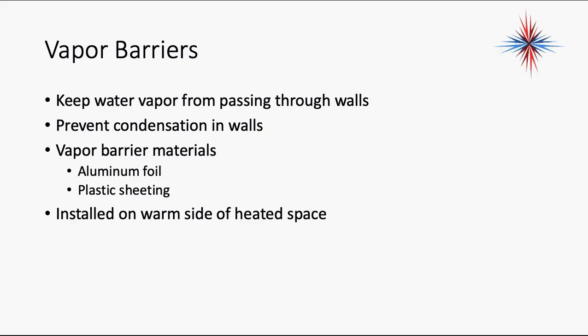My inside environment is warm, my outside environment is cool. If I let vapor into that area, I can actually start building up mold behind that insulation and sheetrock. So we throw a piece of plastic in there, it serves as a vapor barrier. Because believe it or not, vapor and humidity get through sheetrock. It's a permeable surface.